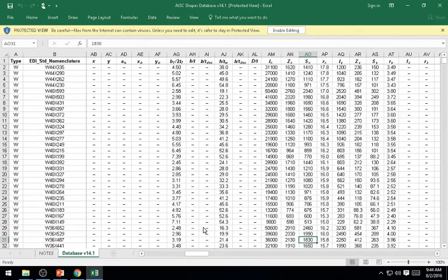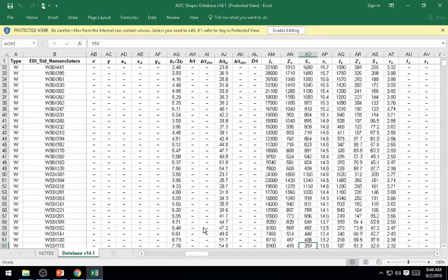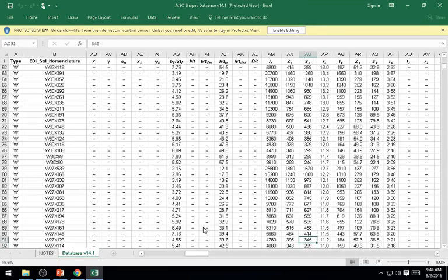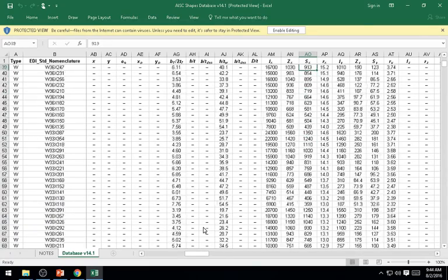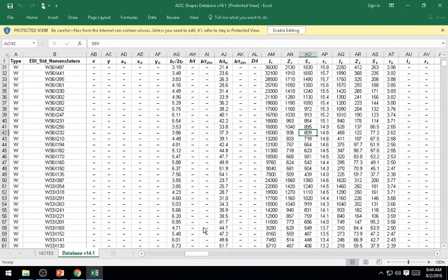And really, all you then have to do is find a shape that has the minimum required S. You would also usually want to select for the lightest shape possible, which means that, I'm going to go through a table of this later, but this W36x182, 36 is the depth, 182 is the pounds per linear foot.